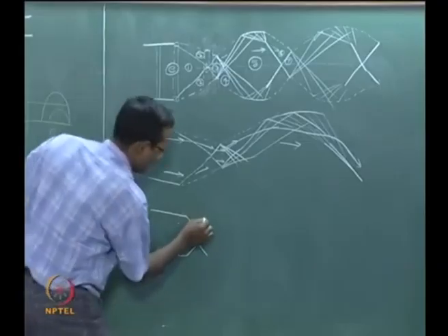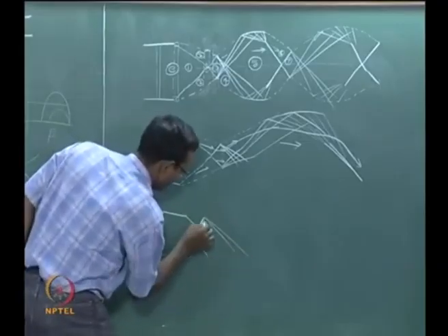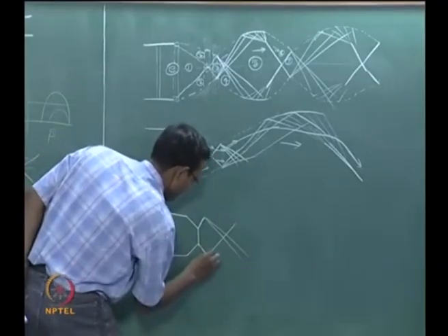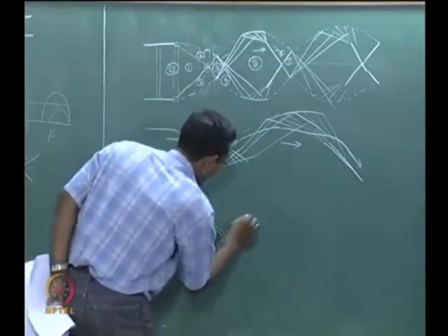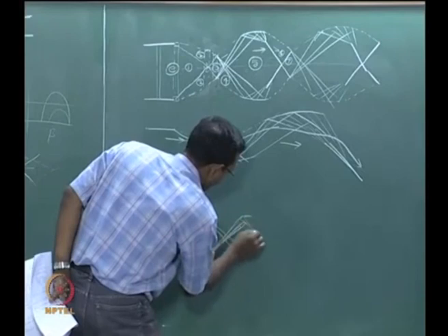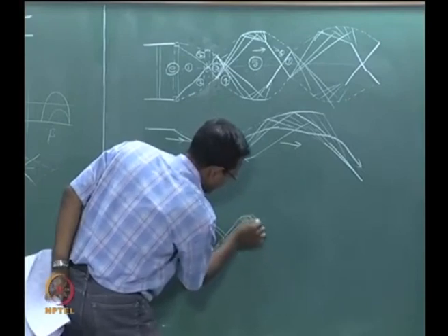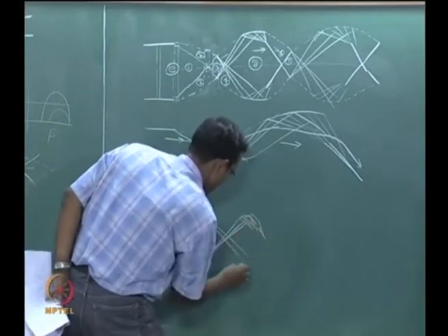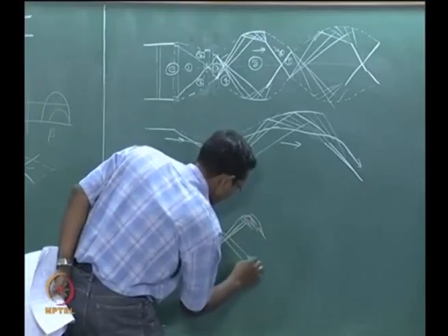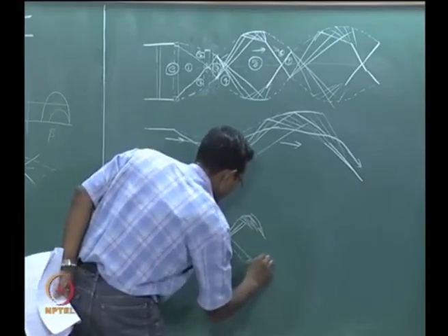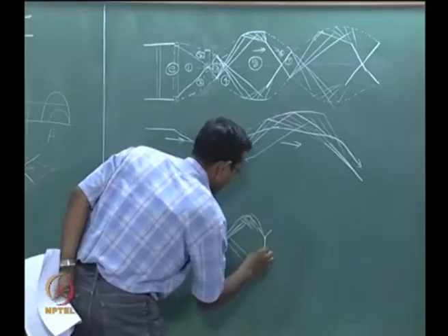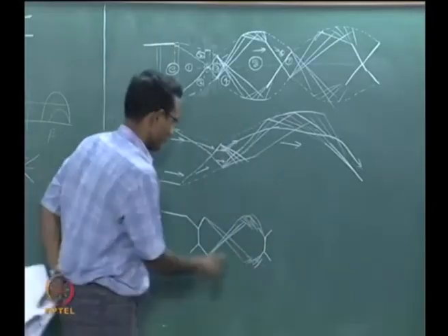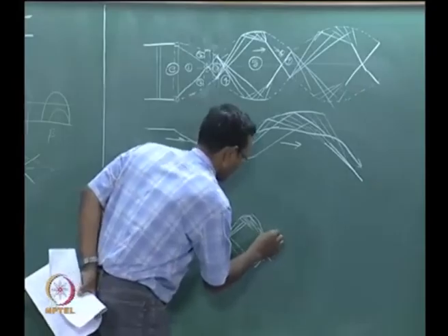Again the same thing happens here, there will be an expansion fan, and that will turn around into compression waves and form another shock. And they will again have this jump typically, and it goes through the whole sequence again.